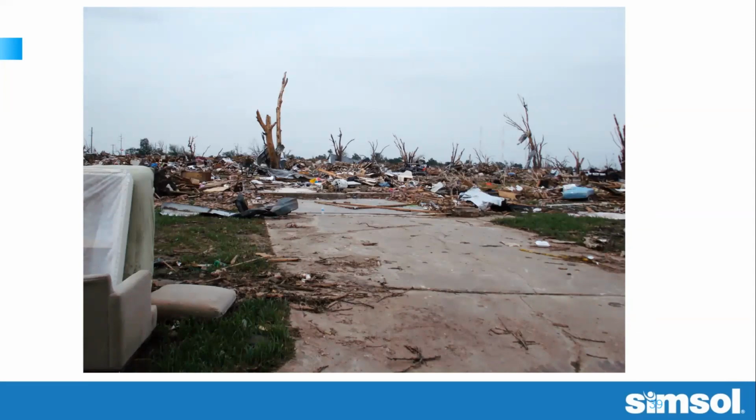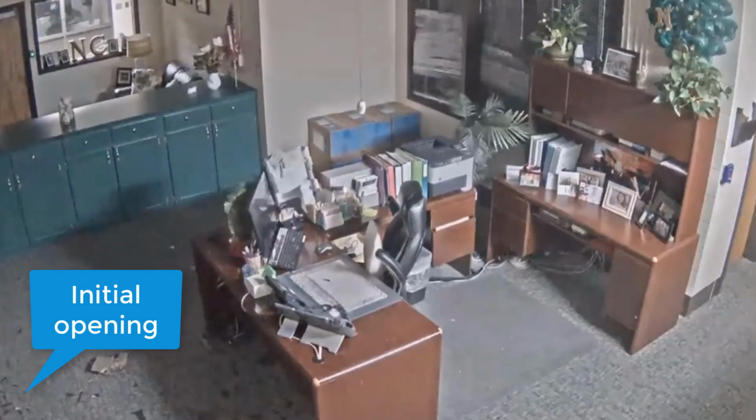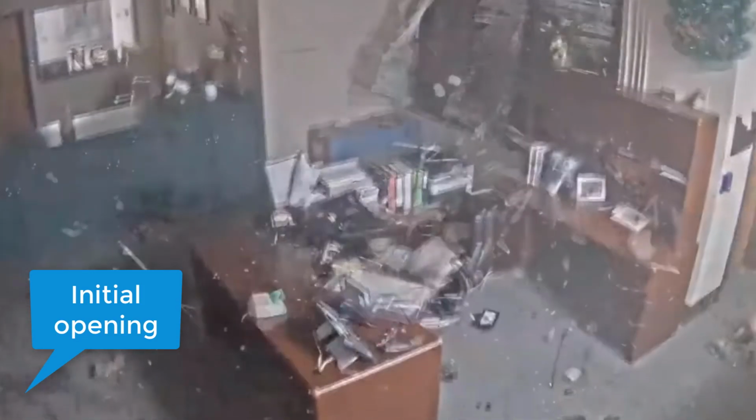Typically the larger openings, your picture windows, the garage door if it's not wind rated, typically those fail first, and then as the house pressurizes as a result of the storm-created opening, that's when you start to see catastrophic damage. It's been my experience that the house doesn't necessarily explode or implode because of a pressure difference. It's usually a result of some sort of opening created, and the wind rushes in, fills the building, and then causes the displacement.